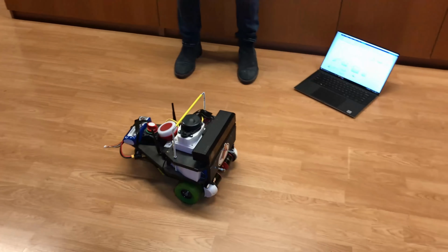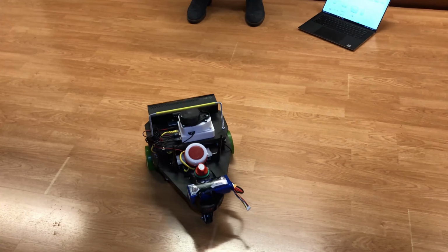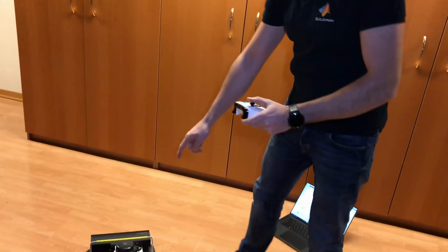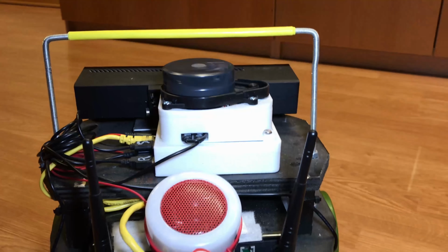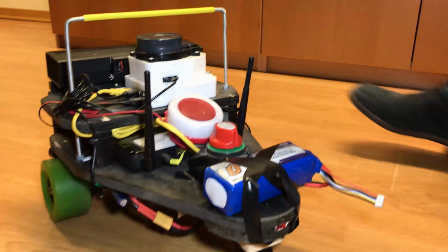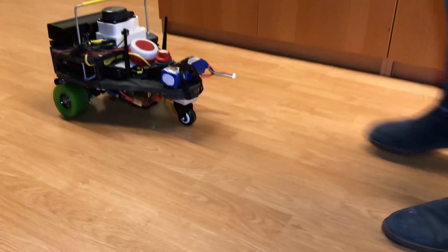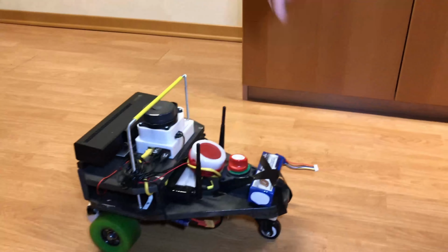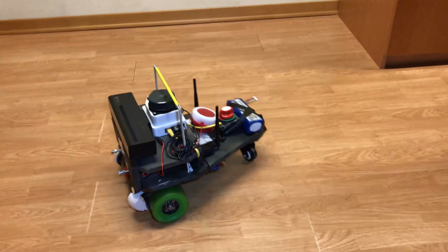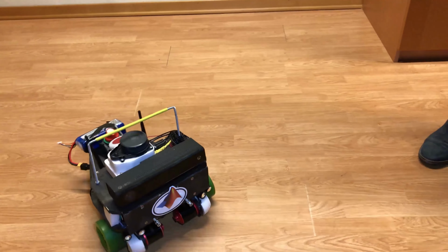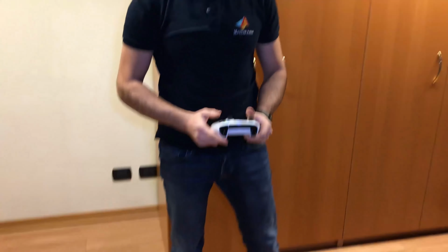Okay, now it's also acquiring data. By means of the lidar that is now running here, you can see it's spinning. We can move the robot and it projects the beams in order to acquire the data. Now it's moving toward the end of the wardrobe, and now it can read the distance from the wall. By moving this robot around, we can acquire the information about the room and construct the map.